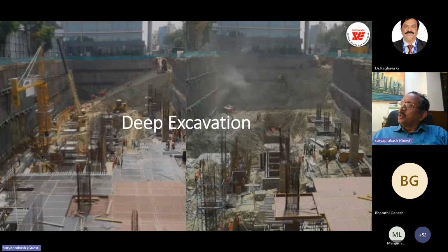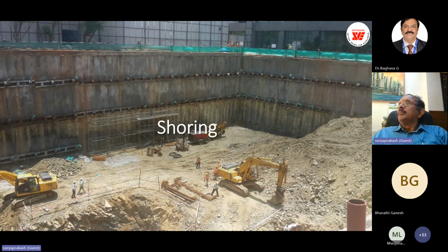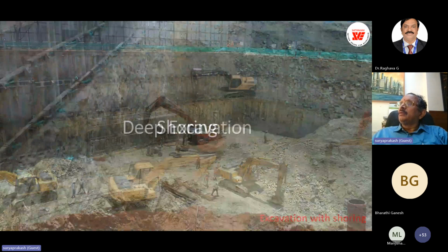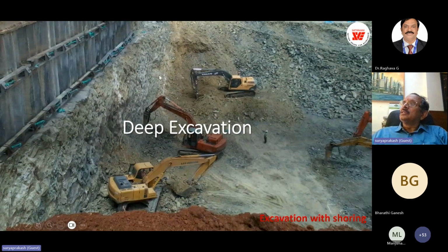Then this is during progress of work, there is no problem at all. So with uniform soil strata, the shoring piles work perfectly. There is absolutely no problem. But when it comes to non-uniform soil, where we have this kind of soft disintegrated rock, the piles are supposed to be socketed to a depth of 2 meters, and the berm is supposed to be there as per the design about 1 meter, and then the sloping as per the design drawing. We can see that there is a mismatch between the actual design and construction methodology and what is implemented.